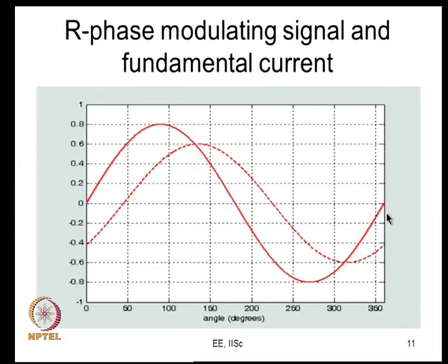of the load. So, let us say the load is an inductive kind of load, an RL load, a lagging power factor load. In this case, it is lagging by some 45 degrees, and the load consumes a certain amount of current, which is given by this. Of course, the load will have a certain amount of ripple on top of this current waveform, and we are just ignoring this, and only the fundamental current is shown here. You can see that the power factor angle is 45 degrees, the current is lagging the voltage by 45 degrees now.